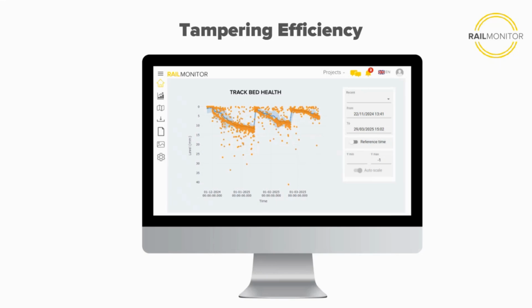This is another view of more or less the same situation. Here all the small dots are trains that are approaching the sensors. And we see very easily that in the beginning of the monitoring period, which was in December last year, we have more or less 0 deflection. And then 1 month later, the deflection is approximately 10 millimeters. Then they decided to make a manual track adjustment, and the deflection again comes to 0.